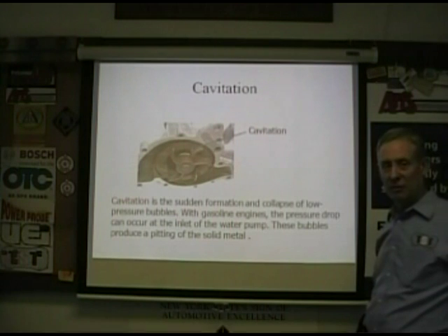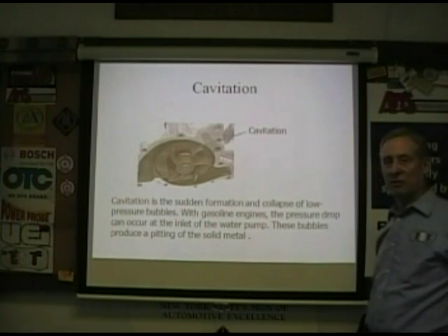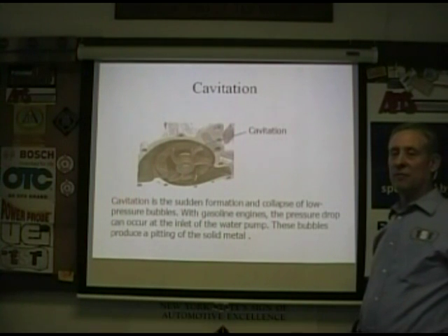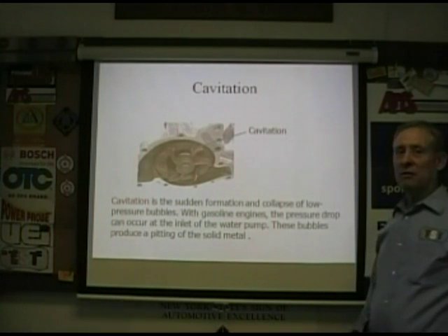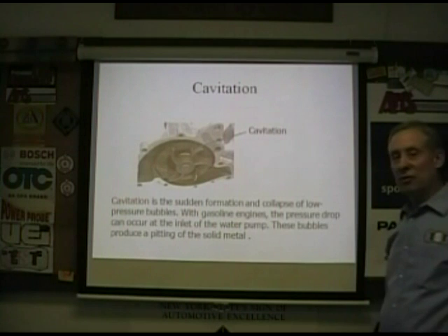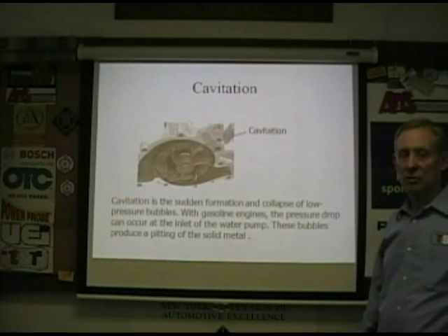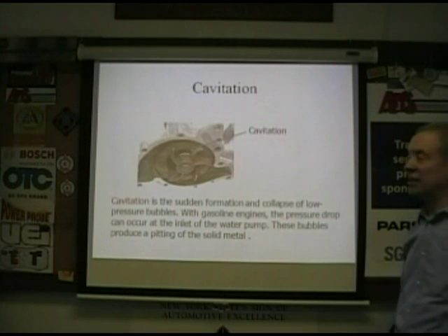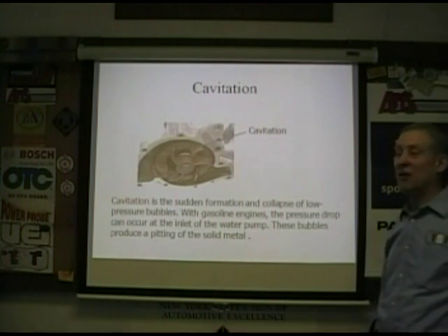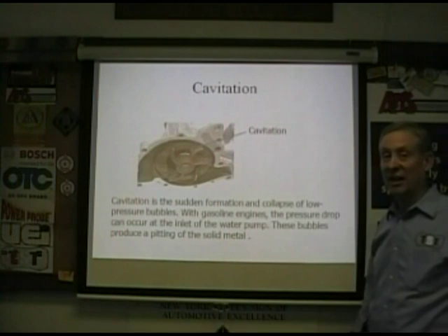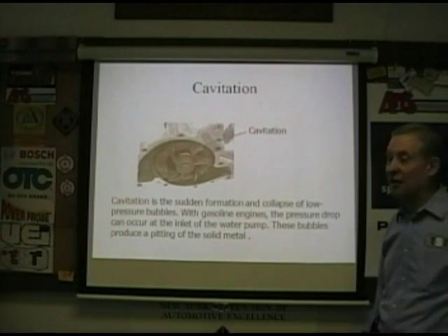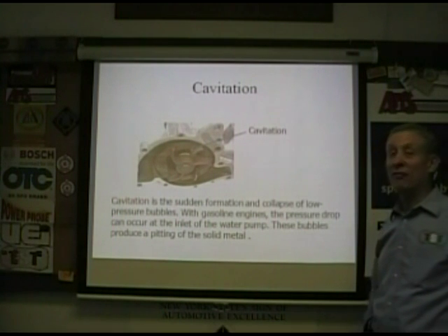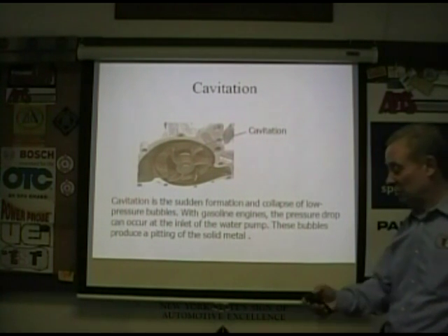If you're using something like an airlift or a machine like a Flow Dynamics that fills them up and takes the air out, and you keep getting bubbles, it's due to cavitation, or you have a part that's been damaged due to people putting the wrong stuff in. You have to look for why there's air getting into that system. You may have a hose clamp letting air get sucked in on some low pressure area. You might have a problem with a radiator cap, a common problem. Whatever it is, you're aerating your coolant, and it's a problem.